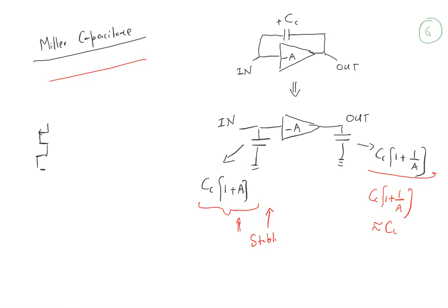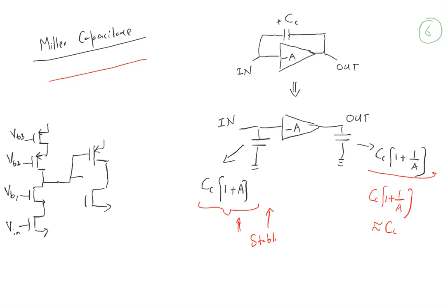Here, instead of adding a capacitance, all of them have some bias voltages, VB1, and here we have the intermediate node. Previously we added a capacitance from here to ground. Why not add a capacitance in between these two stages? Let me use a different color. CC. Make sure this is clear to all of you, because it's again the same essence of what we are doing.